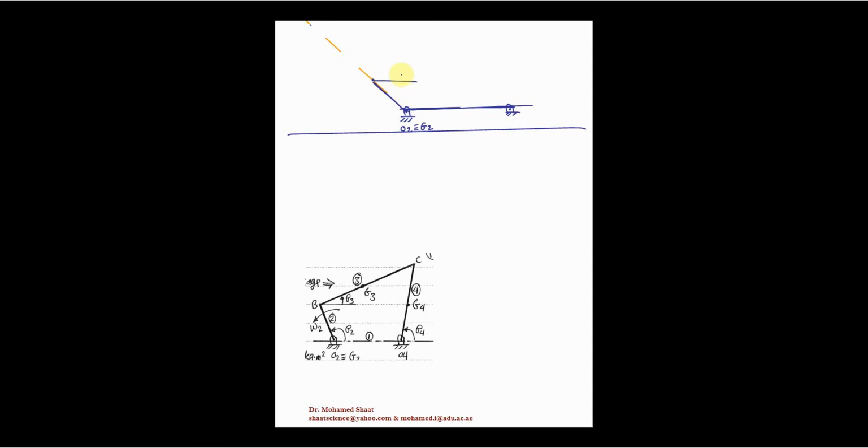Then you're gonna measure the angle theta 3, which is already given as 17 degrees. Then you're gonna draw a line with a length of 100 millimeter, or you can do the same using the compass and draw 2 arcs as I just explained. So in either way, your objective is just to locate point C, which should be located somewhere here. And then you're gonna connect this point C to point B to end up with the link BC in this way.